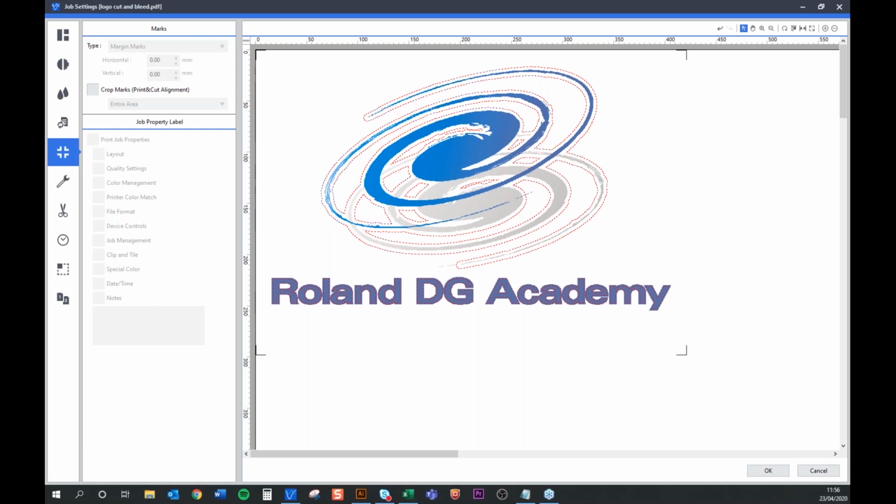It just has a default weight, as you've noticed. So what I might do as a workaround in the meantime from that comment is to put an offset of 1 millimeter. So where you have your margin marks, if I go to the horizontal and vertical offset and put 1 millimeter, it will move those margin marks 1 millimeter outside, and then just make sure that you cut inside the margin marks, which means by 1 millimeter you would lose the margin marks. So I hope that makes sense.